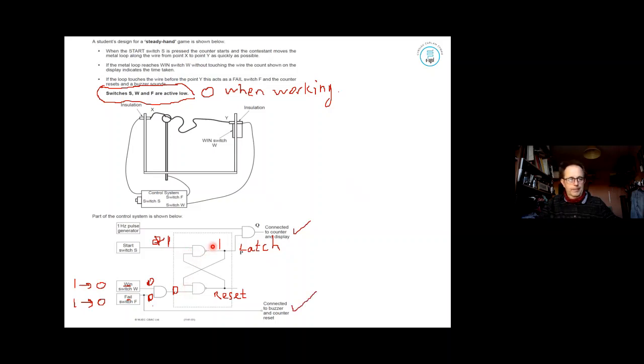When you come to this type of thing, remember that if you've latched something on, you've got a 1. If the input changes, that stays on 1. That's the whole point of this, it works as a latch. So 0 will trigger it, but if that 0 goes to a 1, that will stay on 1 until you reset.